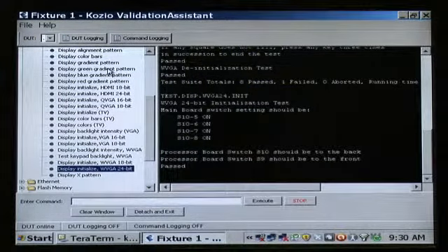We first enter a specific green to black gradient, which shows a smooth gradient as we would expect. We then try blue to black, which also looks good. But the red to black gradient has an obvious problem. This indicates that something is wrong in the red byte of the display bus.